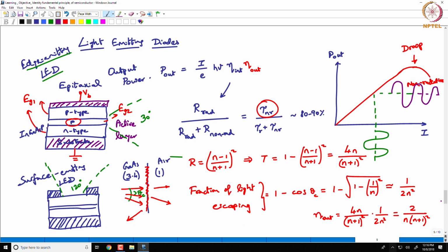But now that we have LED lights, now we can actually convey information. Now we can modulate that light with some information, and then you can maybe enable downloading of information through that LED lamp, which is primarily for illumination purposes, but now we are enabling communication through that. So, you could have these light panels changed to LED panels, and then you could have communication established between that LED panel and your mobile phone.